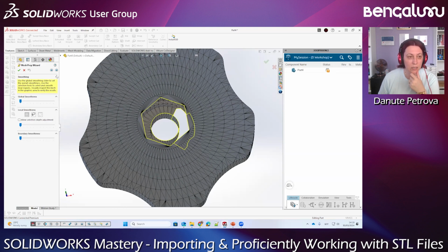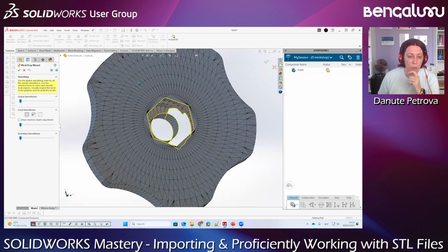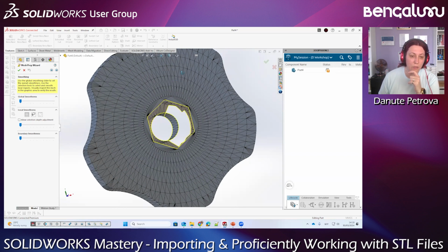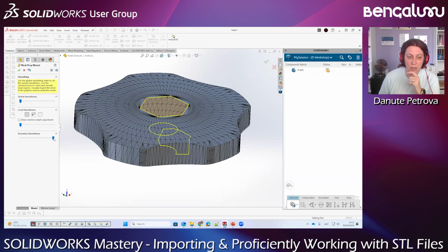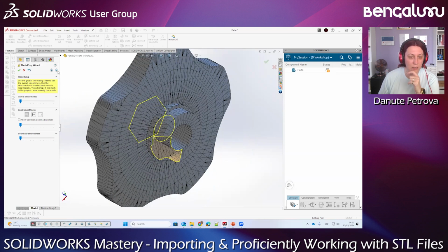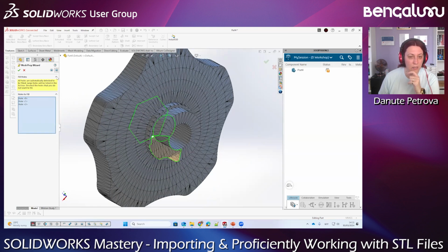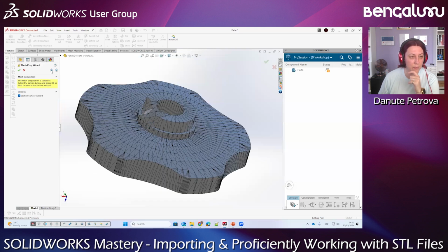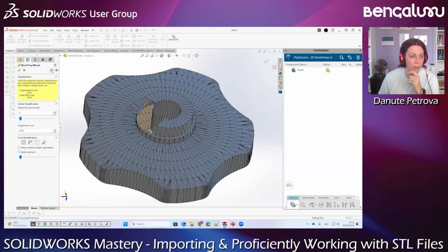It will detect that there are a lot of holes. But on this step, you may want to smooth the boundaries. Just may. In this case, I won't because I deleted some additional faces, and let's see how it will repair it. Not very nice.